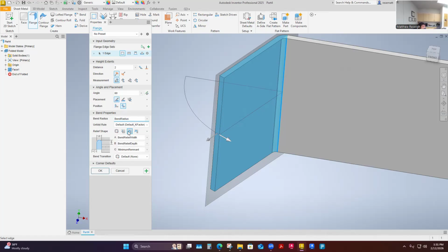Okay, here's a round profile. So this big round, but then I terminate, instead of having a nice square with corner terminations, kind of round those off. There's going to be some strategy involved. Why I think about this is when things bend, sometimes I can prevent the creep of a crack from happening if I radius the end of those rather than leave a square slot cut, which can still tear out at a corner.